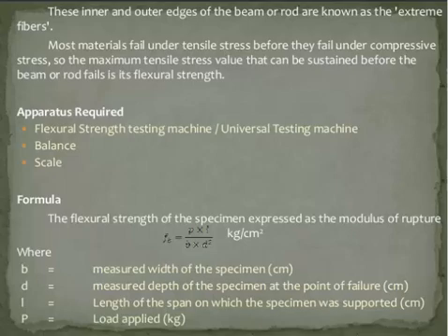So, size of molds. Then a tamping rod is required, 16 mm in diameter and 600 mm in length. Testing machine, right? And the scoop, the trowels, the balance with accuracy of 1 kg, the concrete mixer or the vibrating plates for vibrations if we are not using the tamping rod, right? So these are certain apparatus which are required.